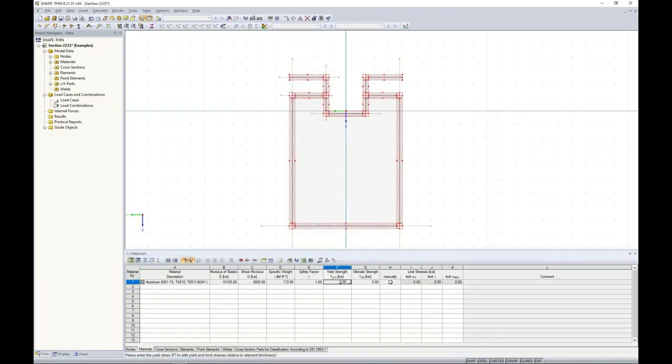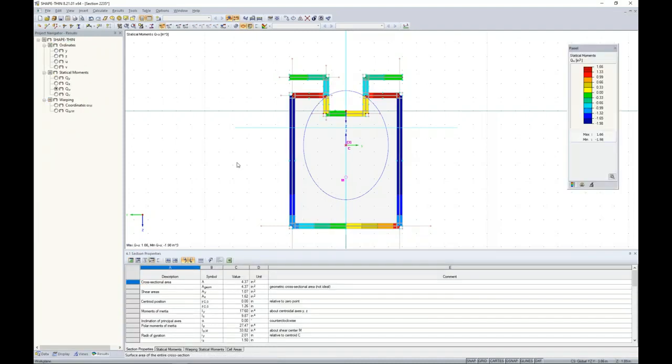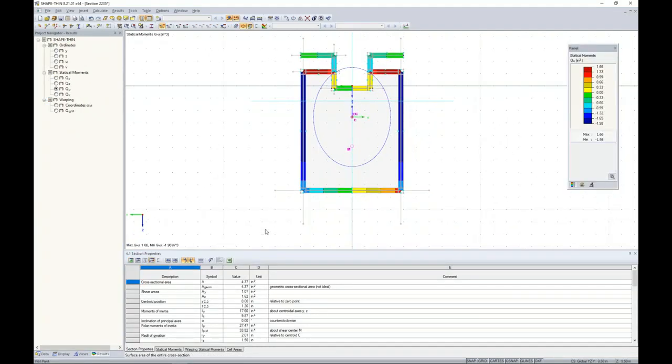Well, the reason for that is because aluminum has different yield strengths depending on if it's for tension, for compression, for shear. So all we need to do is set some type of placeholder here. Fy equal to 30 is perfectly fine. So that's the reason why the program populates 0 there. We can rerun our calculation, and now we can see that we are presented with our results.